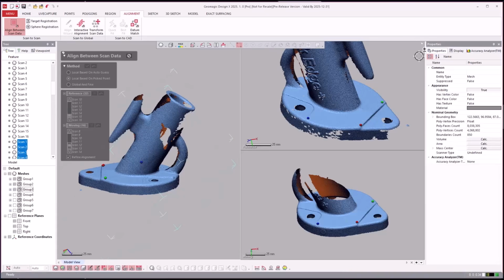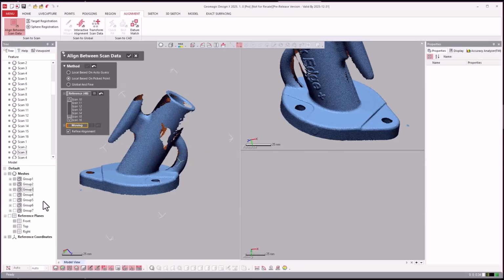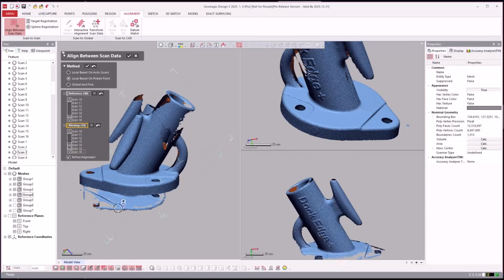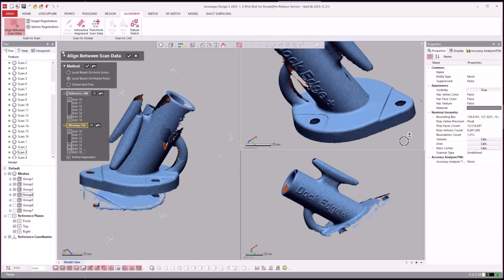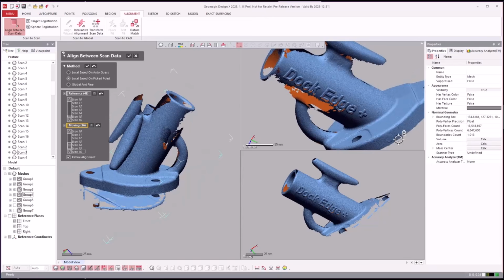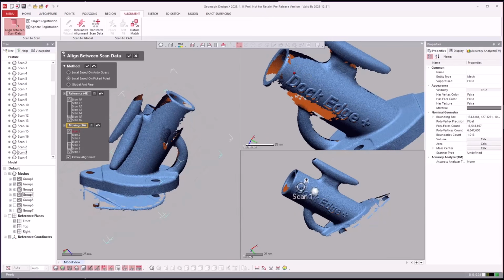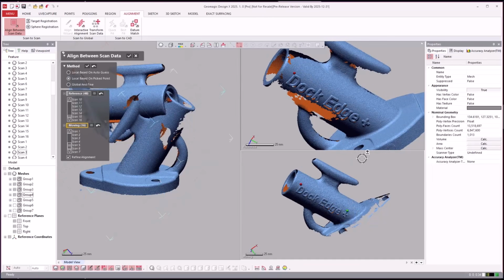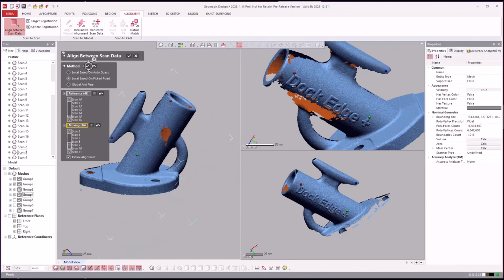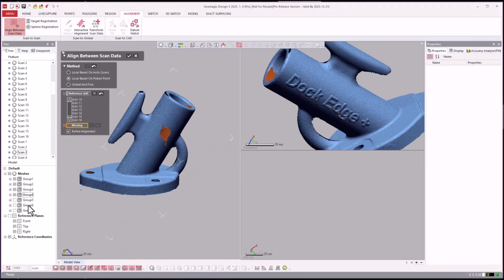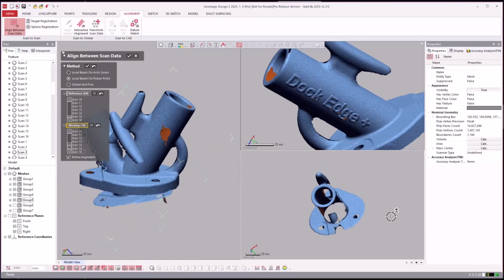There are instances where if you don't get it close enough, then it does not work, right? That is possible. So depending on your experience, you can tweak the way you select those points. If you're measuring parts where you're pushing the limits of what's possible with this alignment, then you might want to zoom in a little more than I am. So we'll just hit that as well. All right. Now we'll just add another and just keep rinse and repeat here.